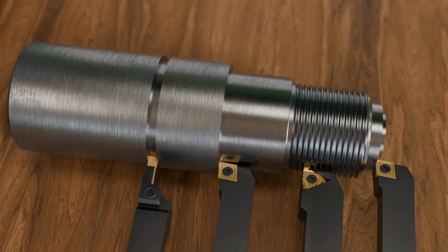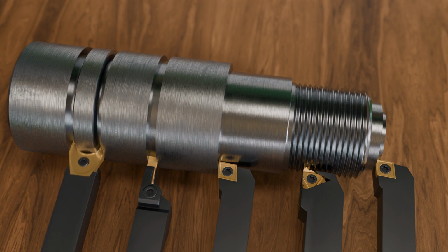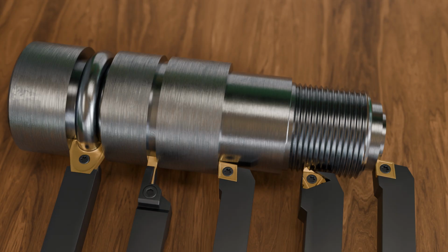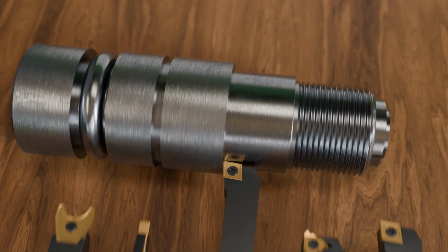In these cases, the cutting edge is shaped as the negative form of the geometry to be produced on the workpiece. Such cutting edges are usually custom-made and therefore relatively expensive. Individual profile turning inserts are mostly economical only in mass production. Turning tools or tool holders for indexable inserts come in different geometries.